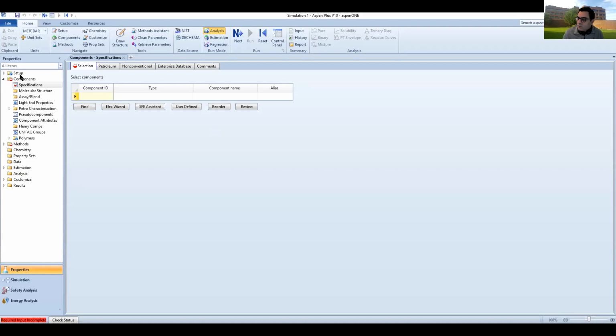And so you're being told that the first thing is to use metric units for convenience. Again, if you recall, in Aspen Plus the two main tabs we're dealing with are Properties and Simulation. You should always start with your properties. This is where I set up or let Aspen know about the chemicals I'm using and the thermodynamic package which I want to use.